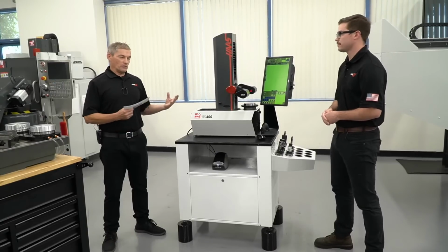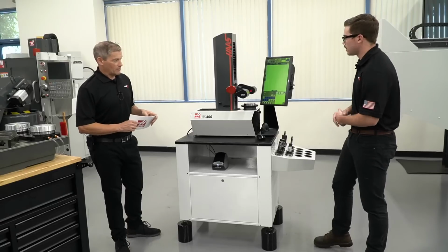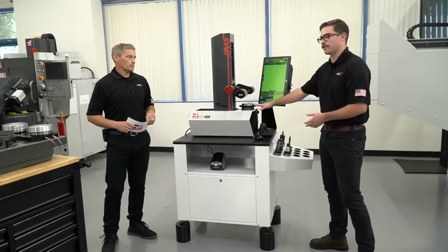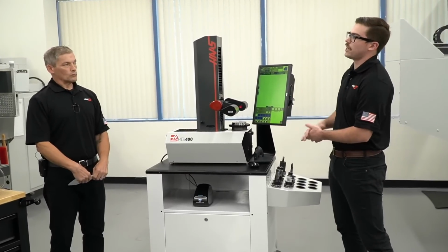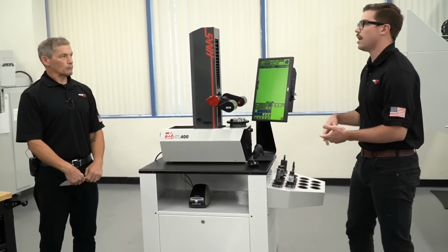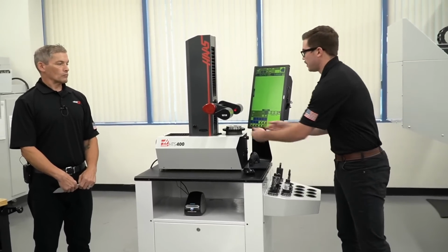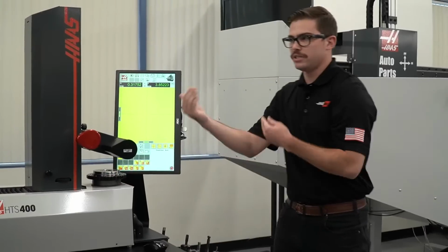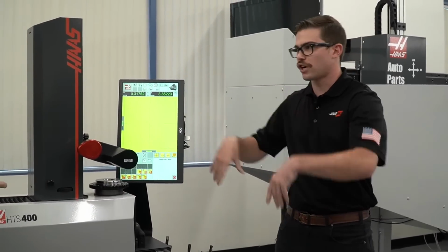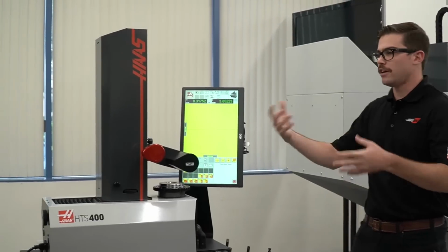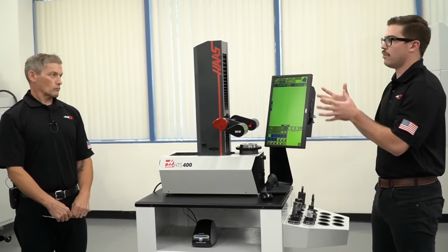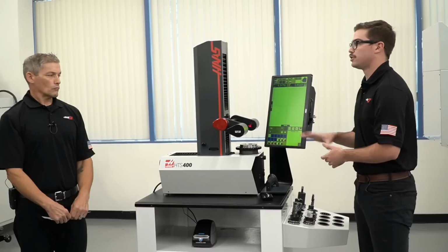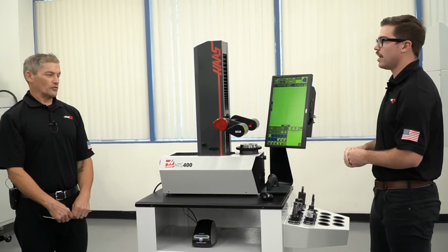Oh, definitely. So why don't we just take a quick look at how this thing works? Yeah, it's pretty easy. I have a tool sleeve in here for a CAT 40 holder because the tools I'm going to be measuring are CAT 40s. But we also have different tool sleeves for a BT30, a CAT 50, or even an HSK. And you can easily swap those out between different operations. So that just drops straight in. Kind of a real close fit. Yep, and then each time you swap it, you quickly calibrate it. It's a very simple process, and even if you have multiple tool holders in your shop, you can use the same tool presetter for all those operations. Cool. Let's look at how it works.